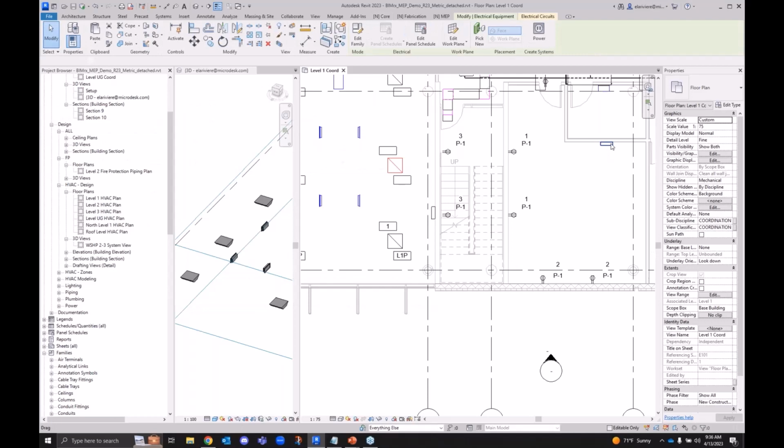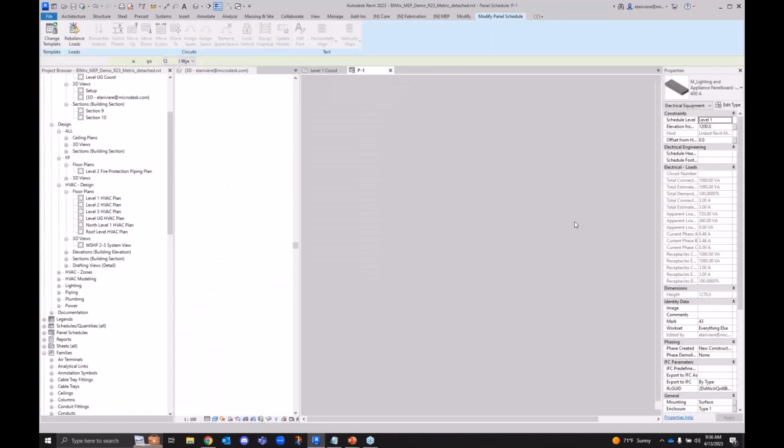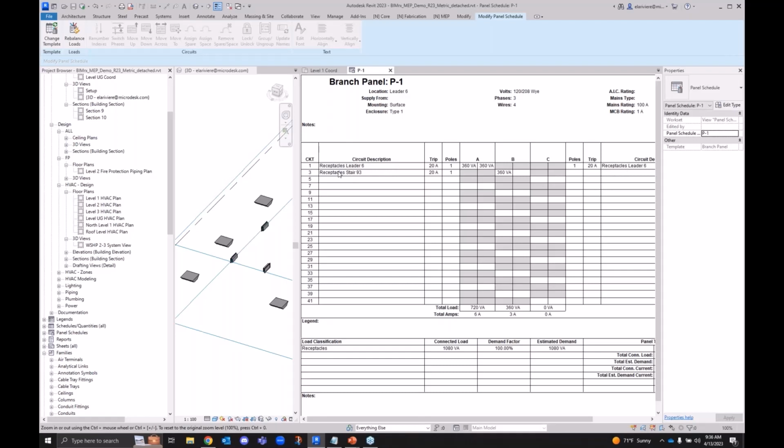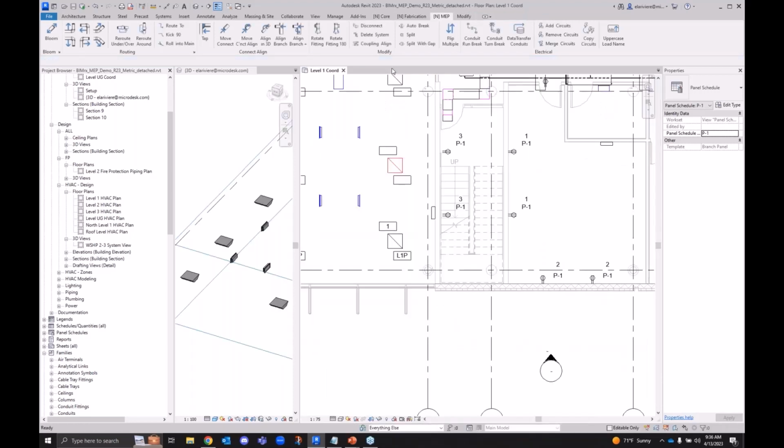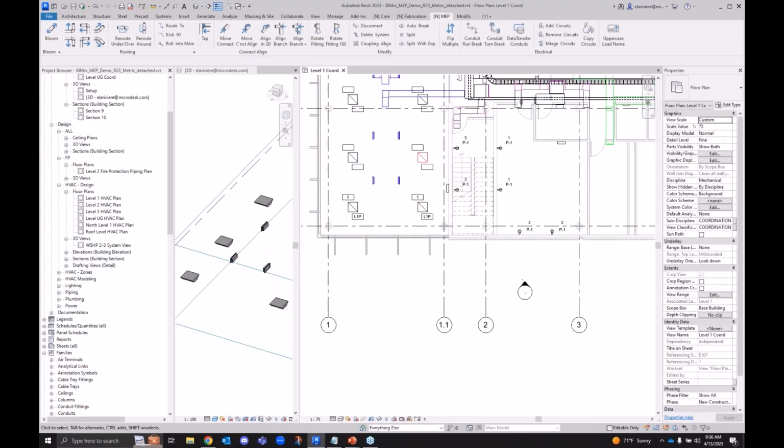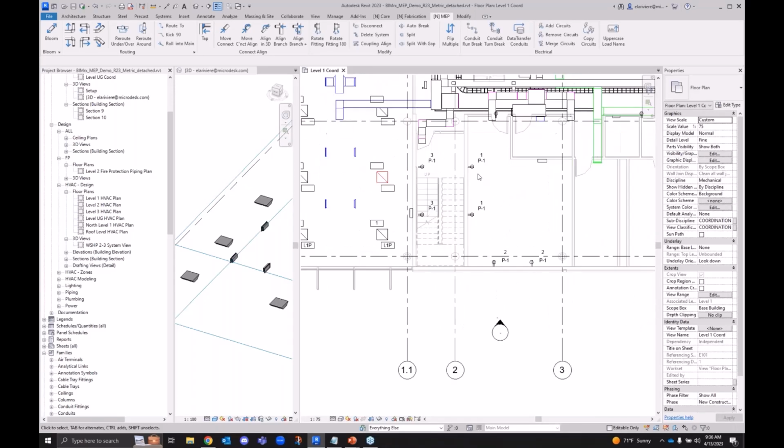If we want to go take a look at that panel, we'll see that circuit 1, 2, and 3 sitting right here. And just while we're looking at the panel, fun little note for you, you're going to have to find something new for your interns, because we can uppercase load names across the project with just a button click. So we're not just creating that new one, we're also adding it to the same circuit. So pretty awesome. Anytime you run into something repetitive, this is going to save a whole bunch of time. I use this all the time working in auditoriums where each row is maybe its own circuit, or in office buildings where each office is, again, usually getting its own circuit with a pretty dang typical layout.